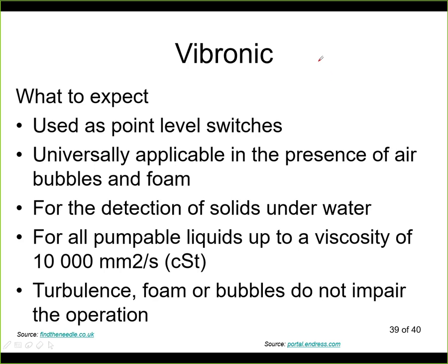So if you have a tank, for example, like this, here is the water level and here are the sediments, then you may actually have multiple sensors of this kind. You may have one sensor in here that detects the liquid level, the water level, and a second sensor on the bottom that detects the sediment level. And when the sediment level is above some threshold, you may schedule maintenance, you may empty the tank, you may remove the sediments, and you may continue in the process.